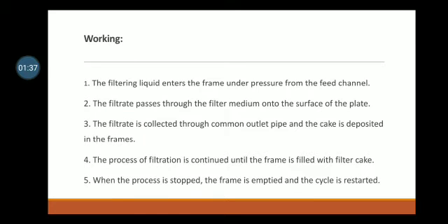Working: the filtering liquid enters the frame under pressure from the feed channel. The filtrate passes through the filter medium onto the surface of the plate. The filtrate is collected through common outlet pipe and the cake is deposited in the frames. The process of filtration is continued until the frame is filled with filter cake. When the process is stopped, the frame is emptied and the cycle is restarted.